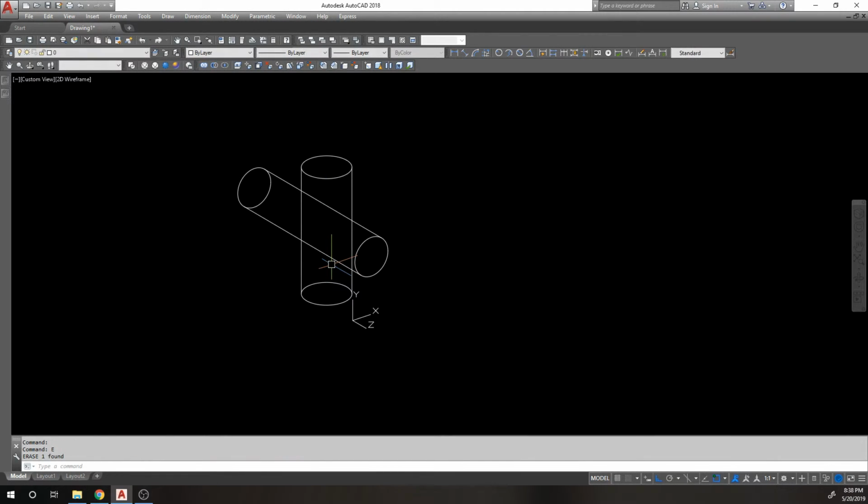If I want to draw that same line with my UCS set to the front, I now need to say .y to here. Because my Z-axis now runs front to back rather than top to bottom. My Y-axis now runs top to bottom.